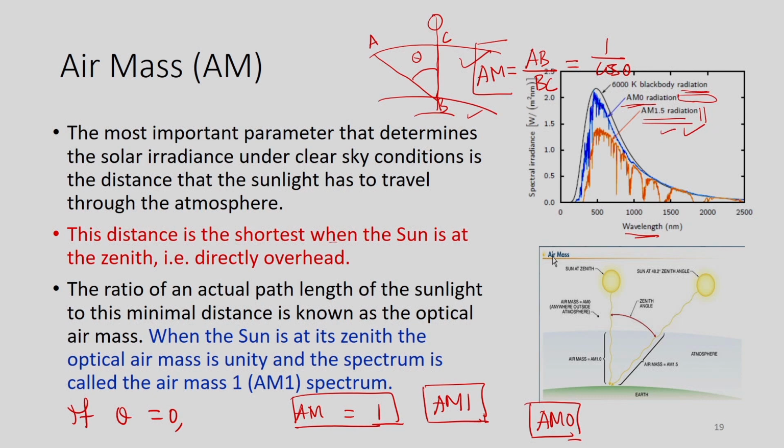So, this is very important, because solar testings are normally done at AM 1.5. We can do very small numericals. So, how to calculate this theta if we know AM is 1.5. So, if we have to do any experiment, and that has to be validated, then we have to perform the experiments at AM 1.5 and at a solar radiation of 1000 watt per meter square. So, that is very important as far as testing of solar collector is concerned.